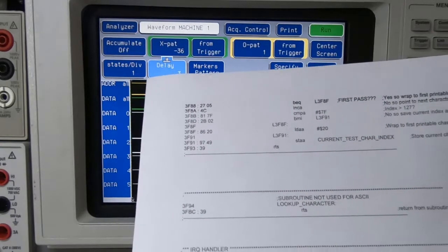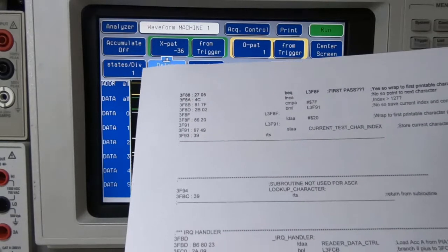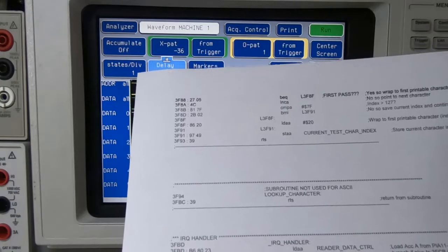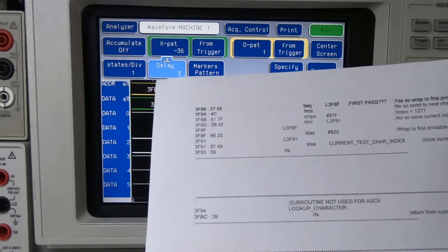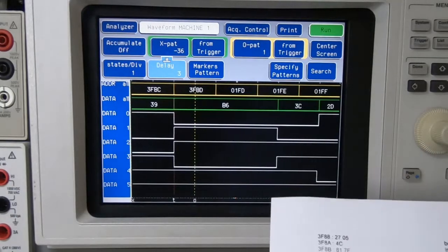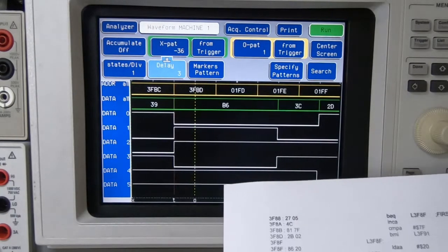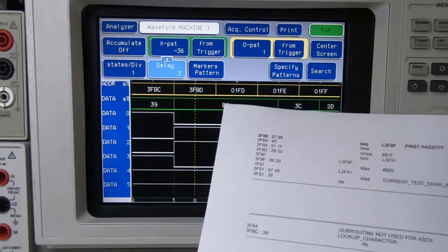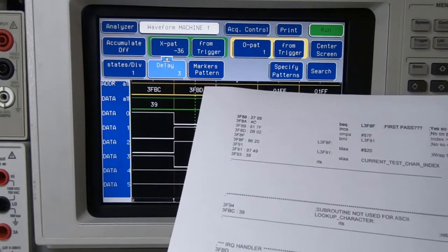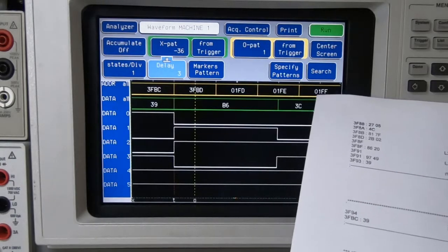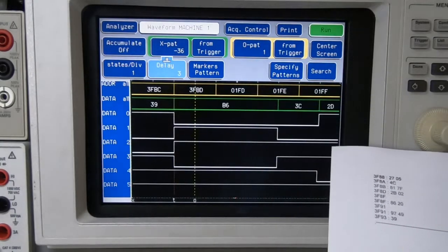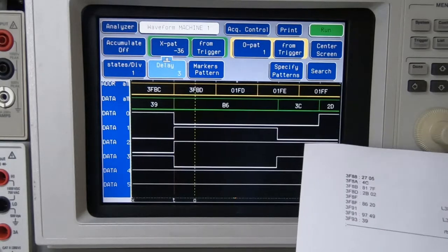So that's just because it's the way that the processor works. When it does a jump, it does tend to fetch the next instruction address, and that's just for streamlining and efficiency within the processor. It's basically doing a lookup of the address it thinks it's going to need next. In this case it's wrong, it doesn't need to look at 3FBD, and in fact when it fetches the data from the stack it will jump back to whatever address was stored on the stack by the calling function.